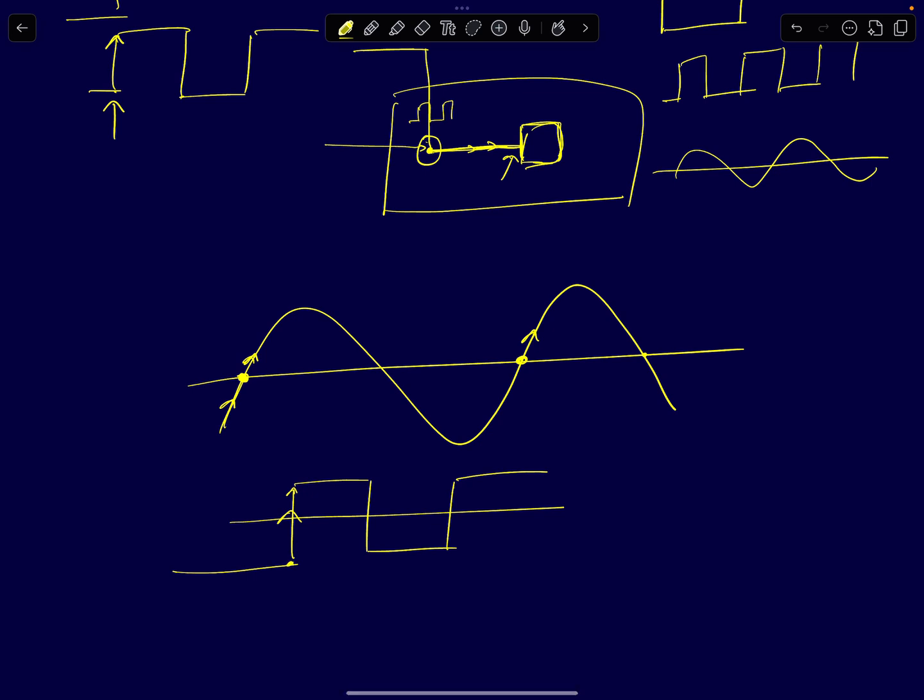So mainly, since it's a clock signal, it's a synchronous system, usually it will operate on one of the edges. So here I'm interested in the time at which the sinusoid crosses the zero, and the time at which the clock signal, the pulse signal, crosses the zero. This information might be helpful. This is something that is of interest for circuit designers who are especially dealing with Schmitt triggers or any sinusoid to square wave converters.